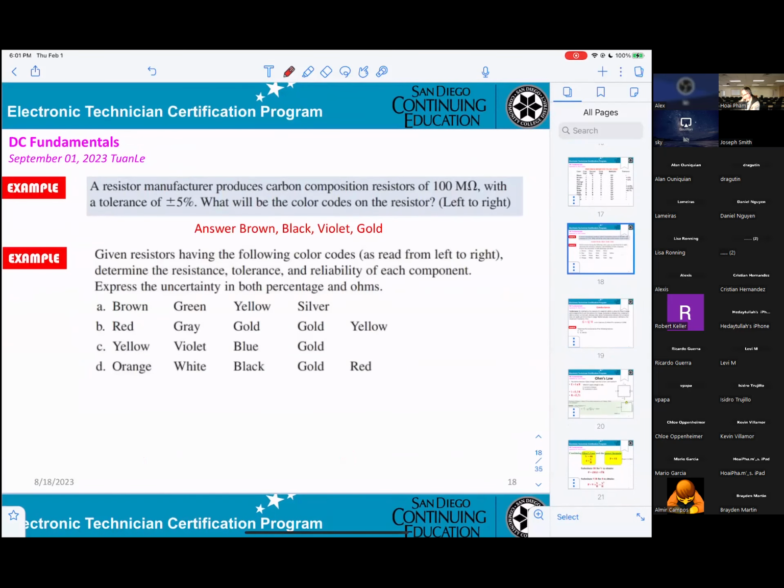So in the previous example, I think the other students' questions were how you went from 10 to 100, making it mega ohms. Is that because mega is 10 to the 6th, but we needed the extra 0, so you went to violet, which is 10 to the 7th, giving us that extra 0? Okay, that will be 100 mega ohm, right? Yeah. So 100 mega ohm.